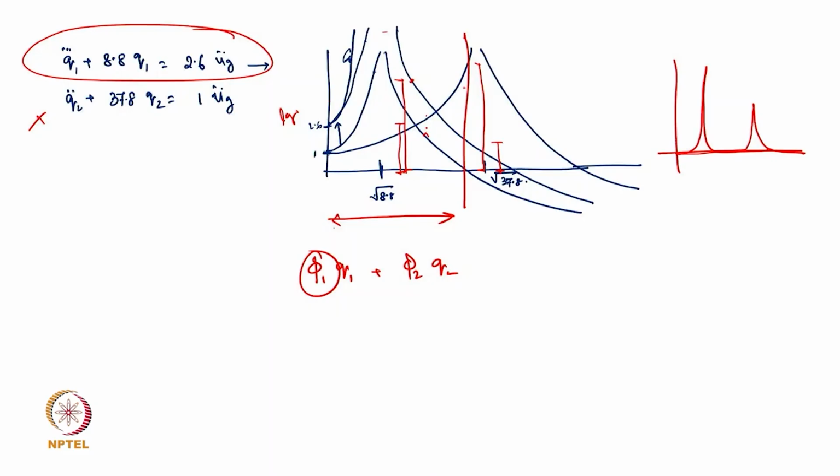If you do the FFT of it, a Fourier transform, you can see how the spectrum comes out. Generally, if you take an earthquake signal and do FFT, you will find that the frequencies lie between 0.5 to 20 Hertz. That's more or less the range. Now, in what range do your building's frequencies lie?